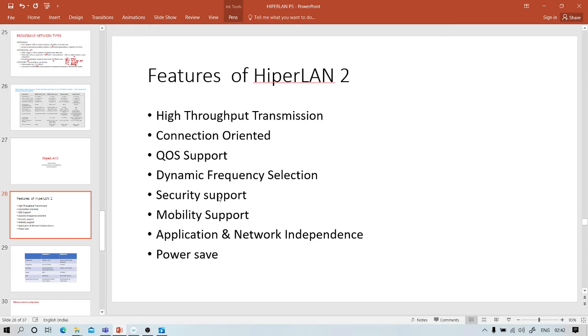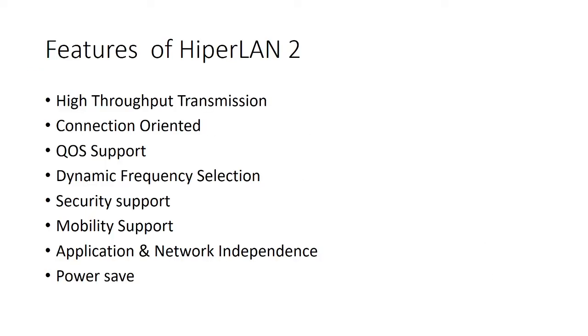So first we are going to see Hyperlan 2, why we are using this Hyperlan 2, since it provides access for the features of broadband radio access network, BRAN network, as well as wireless ATM. So these are the features of Hyperlan 2. Hyperlan 2 operates with an operating frequency of 5.15 to 5.35 gigahertz, and data rate up to 54 Mbps.